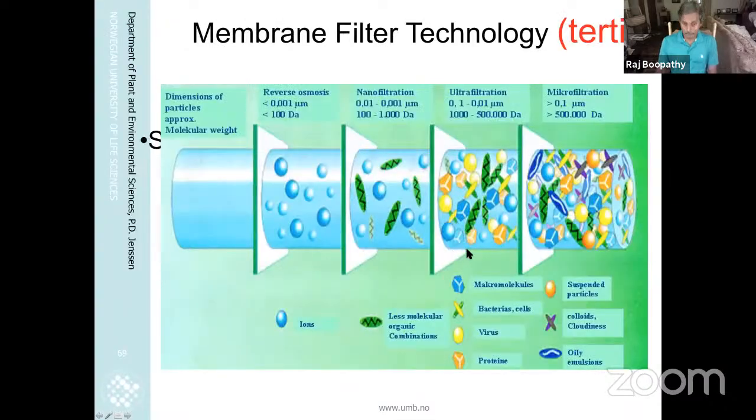And now in states like California, they have water problems. So what they do is treat the wastewater, and the treated wastewater goes straight into the drinking water plant for treatment, and then the water goes to drinking water. This is total recycle of water. All right. So after they go through primary, secondary, tertiary disinfection stages, it goes through the membrane filtration unit, which is tertiary treatment. They use various size membranes from microfiltration to ultrafiltration, nanofiltration, and then reverse osmosis. And then the water comes out, supposed to be as clean, the wastewater completely cleaned up.